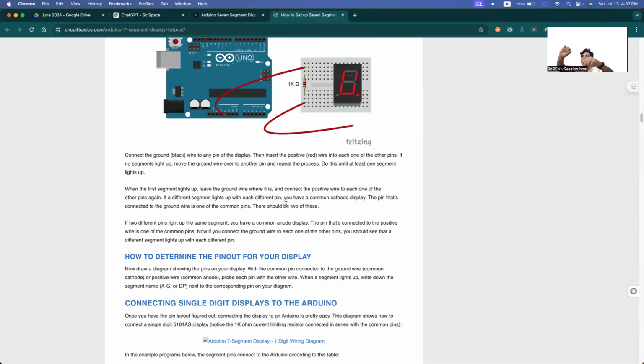So first of all, I will take a seven-segment display. I will connect the display like this, this is my pin number. It's a ground pin. I'm going to connect the ground with the ground, and the other pins, the anode, with the plus. But if it's not working, then I have to check with the other pins. If I get the output from there, then I have to think about that. Let's try with different pins, and if it works consistently as in the procedure you have started, then you can understand, okay, fine, it's common cathode.